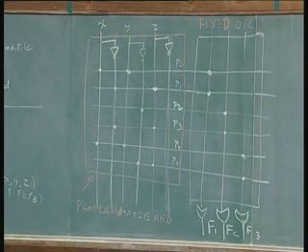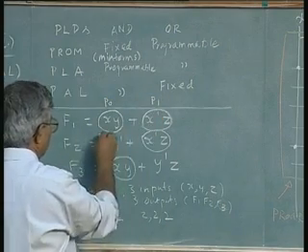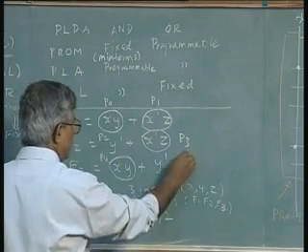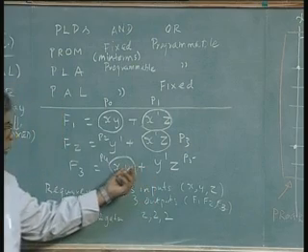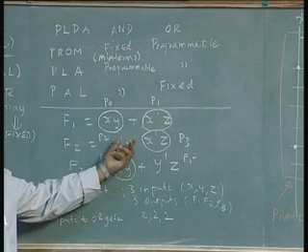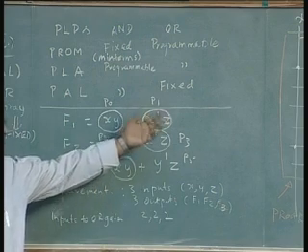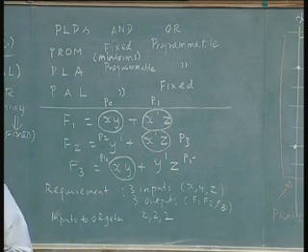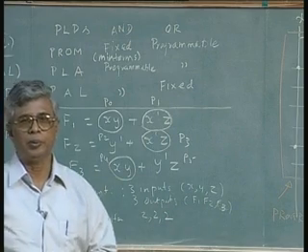Identify this as P0, P1, P2, P3, P4, P5. Each term has to be generated. So here the simplification would be to reduce the number of product terms for each output. In the programmable logic array approach, the technique would be to make as many common terms as possible.